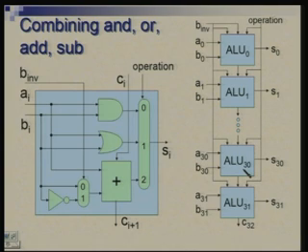Okay. So, now what we have done here is we have taken care of the core of these 4 instructions, AND, OR, add, subtract, and in fact strictly speaking we have actually accounted for not just these 4 instructions, but an additional 4 instructions which correspond to their immediate version.